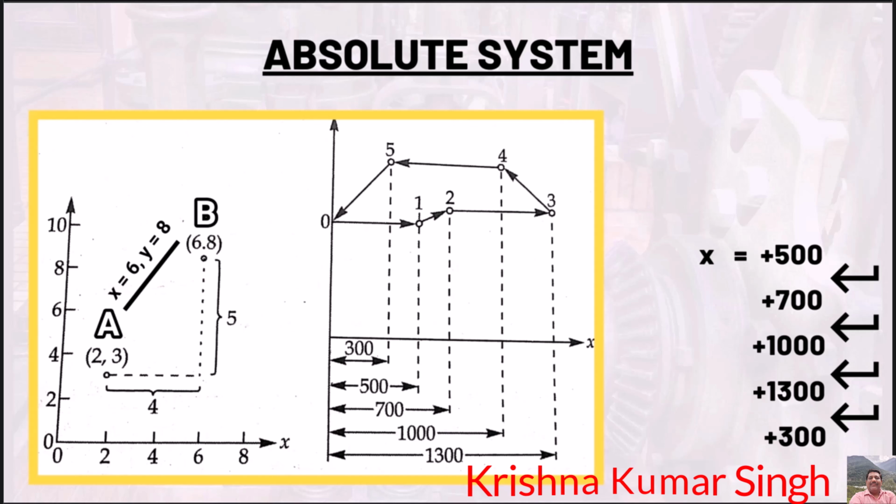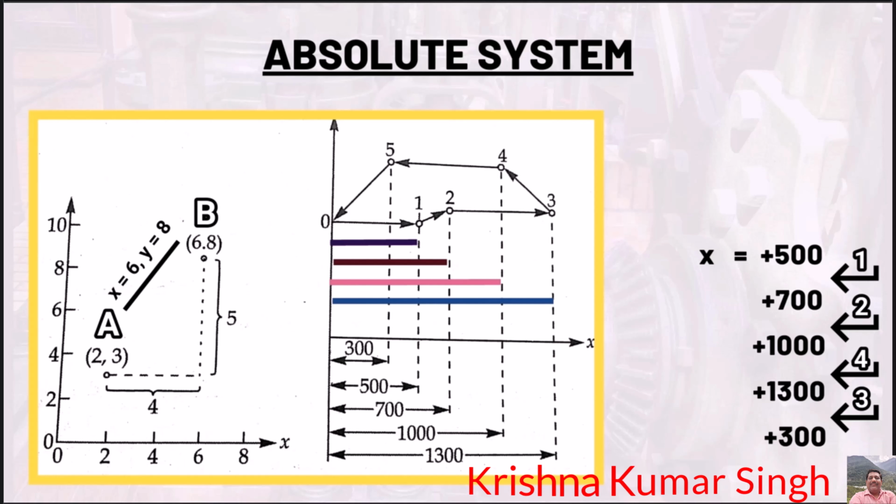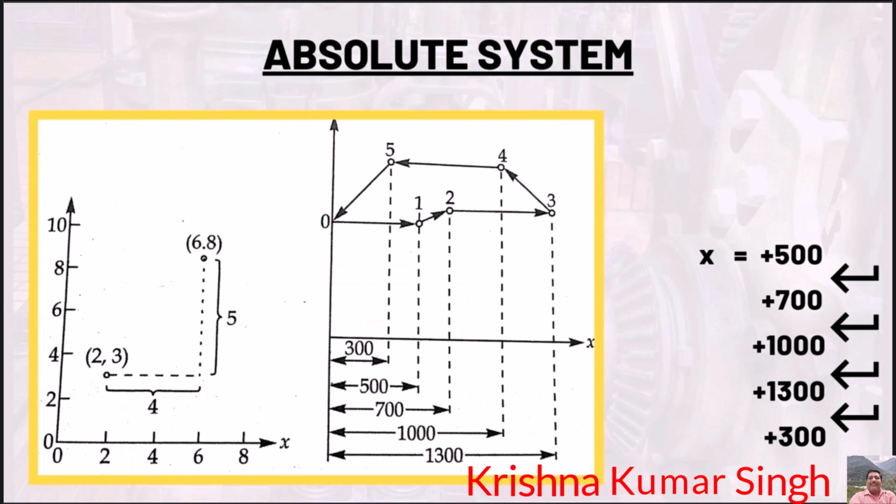Now for drilling 5 holes in this type of system at different locations, the commands for the x direction would be 500, plus 700, plus 1000, plus 1300 and plus 300. The main advantage of this system is that interruptions caused by tool breakage, tool change or checking the parts do not affect the position at the interruption. Also, dimensional data can be changed very easily.